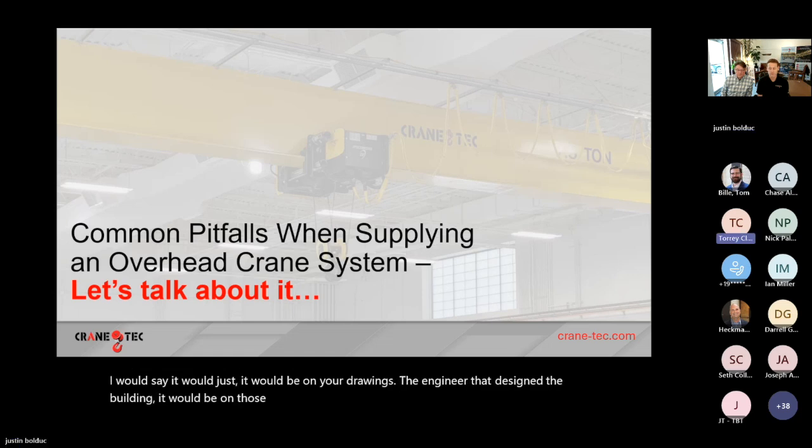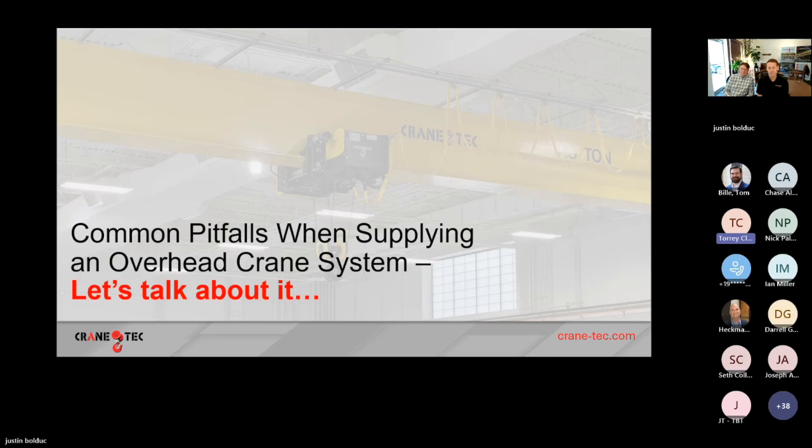It is. We're seeing kind of a bowing effect, but I still think it stays within the 3/8 tolerances. And I would assume that the crane, as it's running up and down it, is going to put it where it wants to go. But I just thought that was kind of a long span, 45 feet. The runway beams are massive, so it works. I've just seen it tied back more often on other jobs. Yeah, thanks for bringing that up. That's a good point.